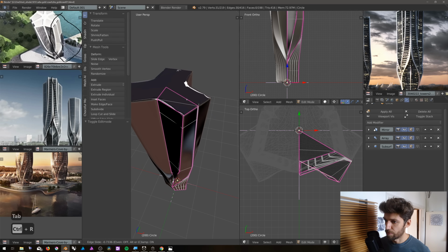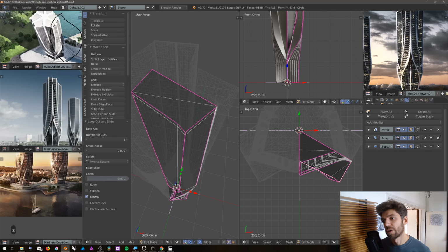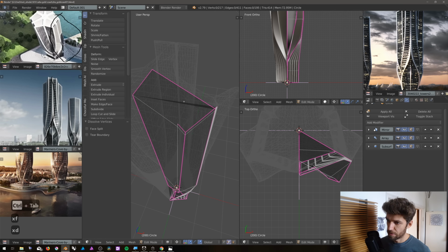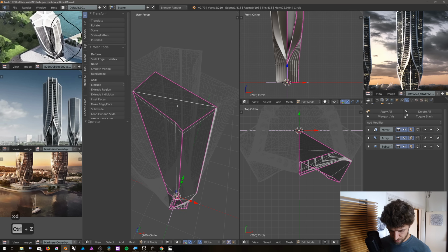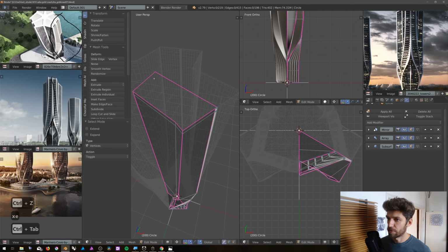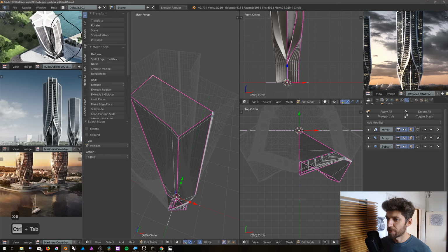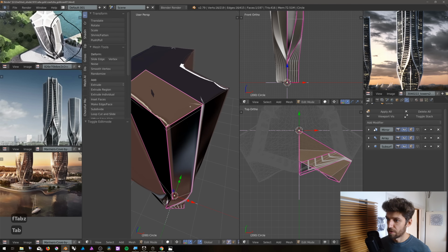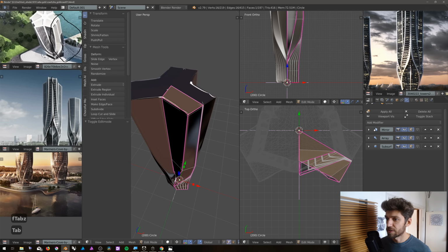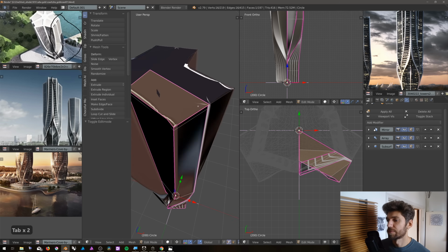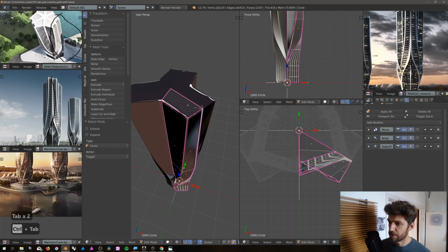Yeah, now one of the ways to start to fix this is to create an edge loop here. Let me dissolve this. What happened? X edge. Let's just redo it. Yeah, we have so many vertices here. I'm never actually gonna sort it out too well. Something like this. Yeah, and the issue is that the density of the mesh here is significantly more than the density of the mesh there. That's why it's doing those funny artifacts.